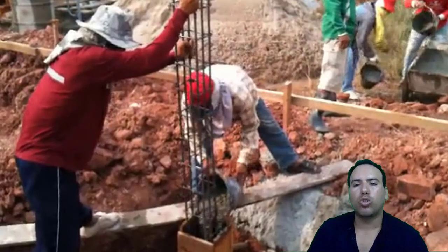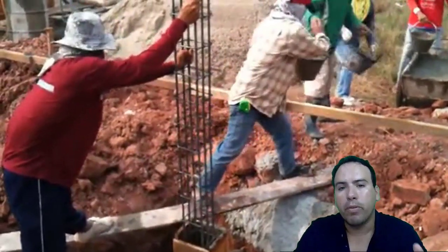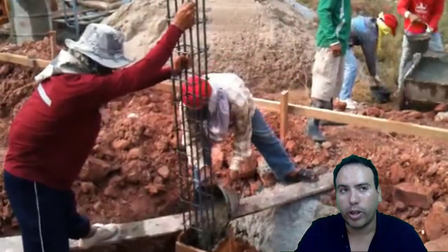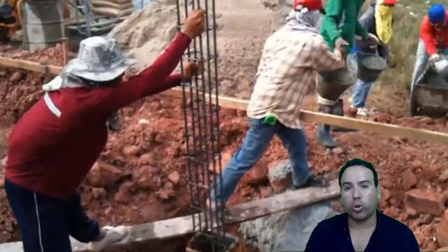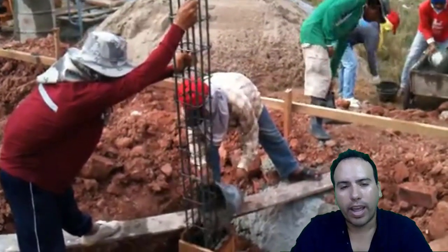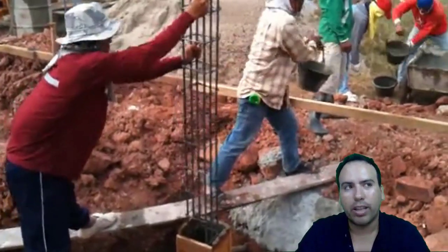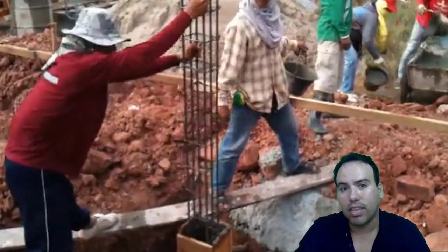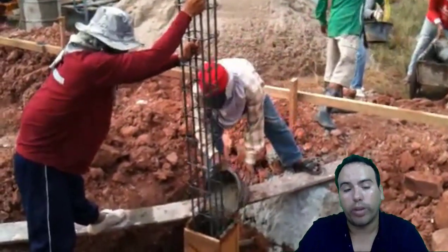of footings. You also have to check the mechanical strength of the soil before doing all the calculations of the structure. There are tests and laboratories dedicated to that before any construction. So before entering the construction site, you gotta do the mechanical tests to check the bearing capacity of the soil.